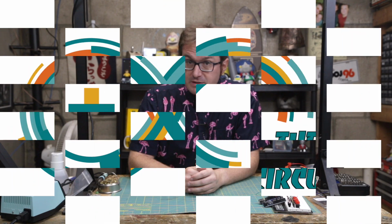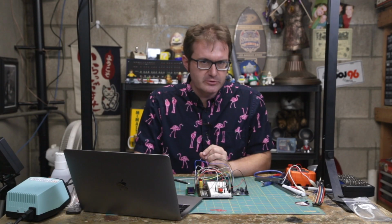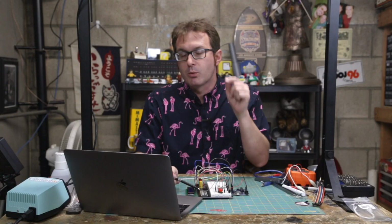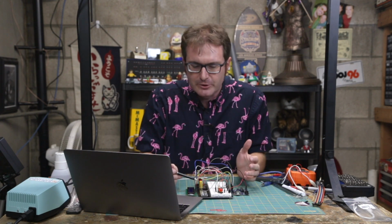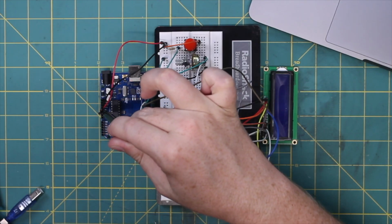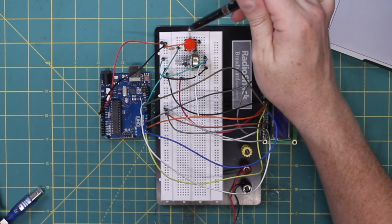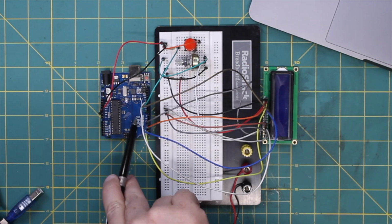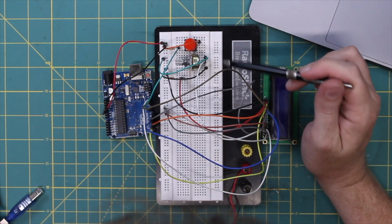Now let's wire the circuit. This is a fairly complex circuit, so I'm not going to go through all of the details here. I will refer you to the show notes so that you can see a much more clear version of this as a diagram. We have power and ground coming from the Arduino into the breadboard. We have a switch connected from the 5-volt to pin 8 on the Arduino with a pull-down resistor to prevent floating.